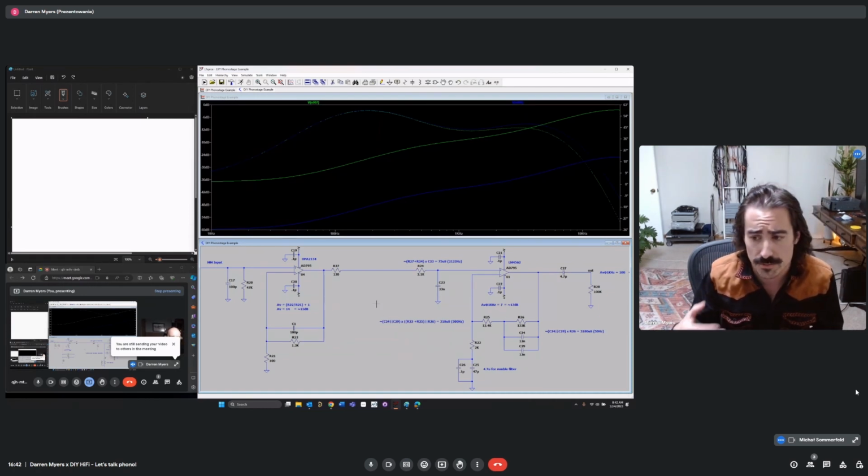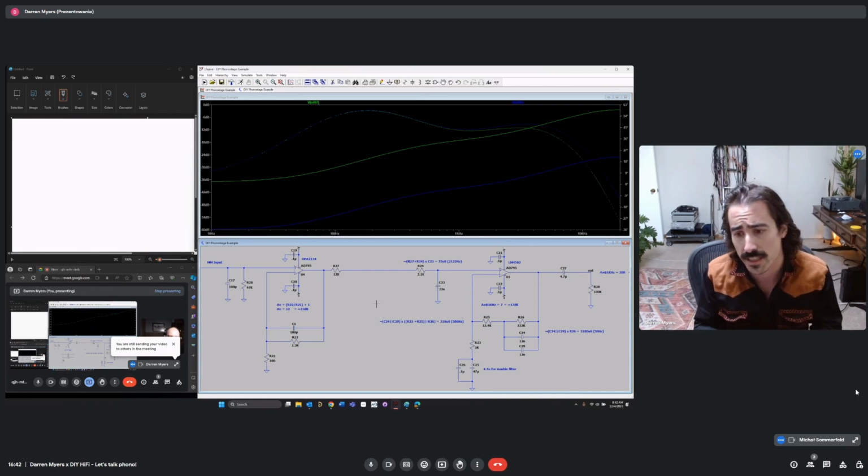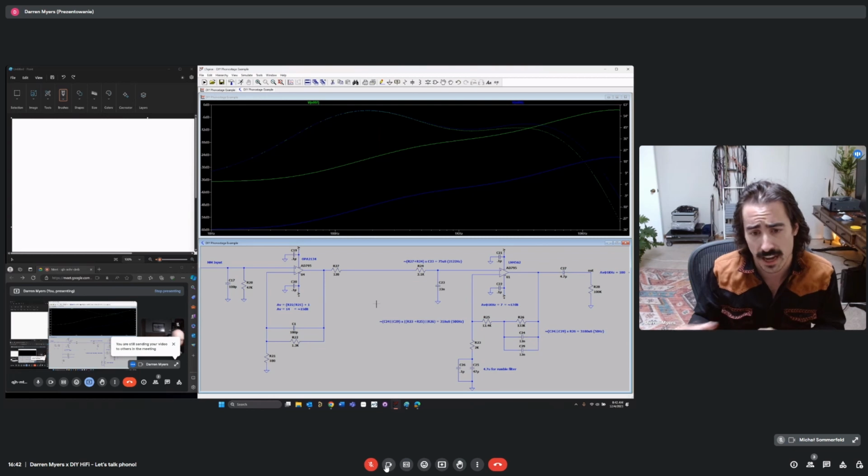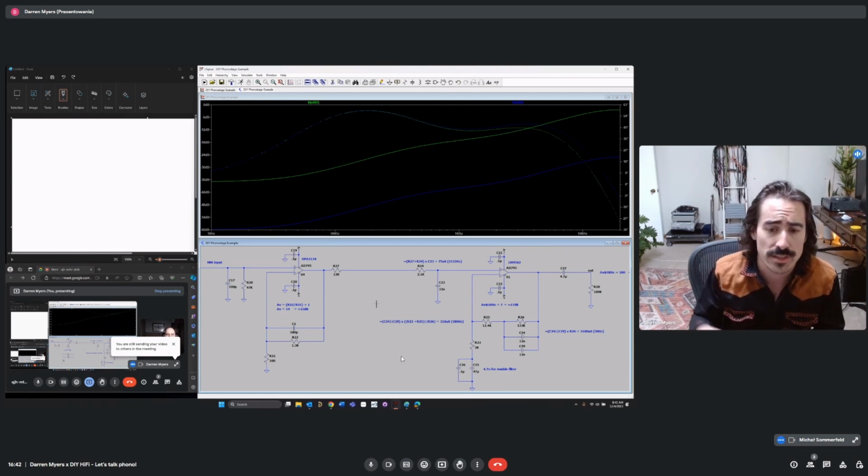If you were to have a signal in the many megahertz, you could easily run into a situation where an amplifier starts to go into slew rate limiting, where it becomes very nonlinear, and in that state, it's going to actually demodulate that RF at high frequency and roll the low frequency components on that signal down into the audio band.